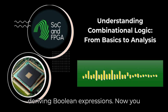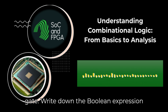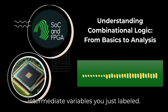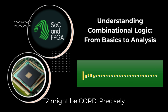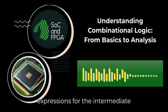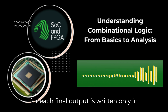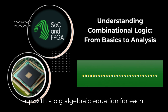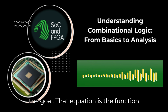Step 2, deriving Boolean expressions. Now you work from the inputs forward. For each gate, write down the Boolean expression for its output using its inputs, which might be the primary inputs or those intermediate variables you just labeled. Okay, so T1 might be A AND B, T2 might be C OR D. Precisely. You keep doing this, substituting the expressions for the intermediate variables as you go, until the expression for each final output is written only in terms of the original primary input variables, like A, B, C, etc. So you end up with a big algebraic equation for each output, based only on the inputs. That's the goal. That equation is the function of the circuit.